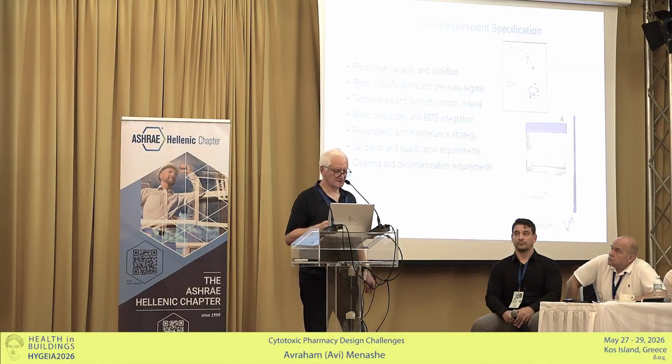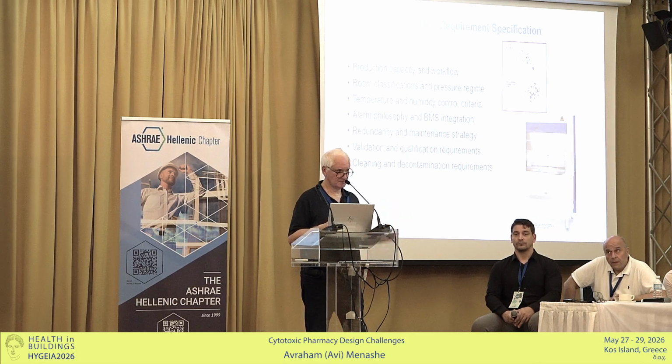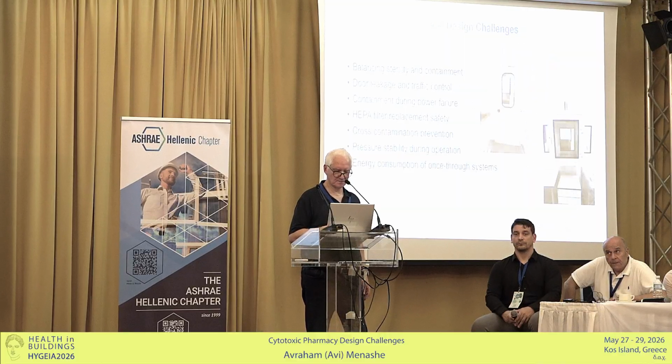And also there is an alarm philosophy. Once the pressure changes below certain set points, you need the alarm. Maybe there are some problems. You can see it on the BMS, but don't forget that the BMS alarm goes to the maintenance people and not to the operator of the pharmacy. But then you get alarms and you know exactly that you have some troubles.